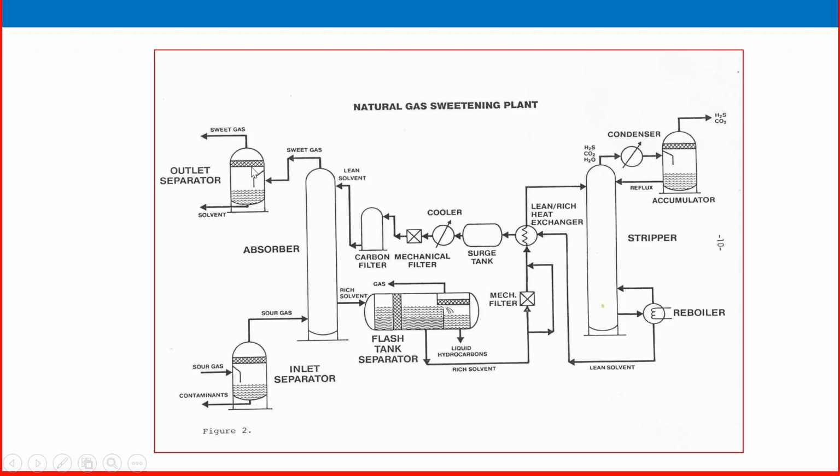So again, any further solvent is there. In case amine is carried over with the sweet gas, we can collect the amine back here. If amine is lost, we are losing money. So we always have to collect amine back regularly from the exit system, so the amine will collect here, using the inlet plate and the demister pad. This is called a demister pad. Both systems it will pass through, and whatever heavy liquid amine is collecting here at the bottom, we can separate using a level control system. So that is the absorption system.